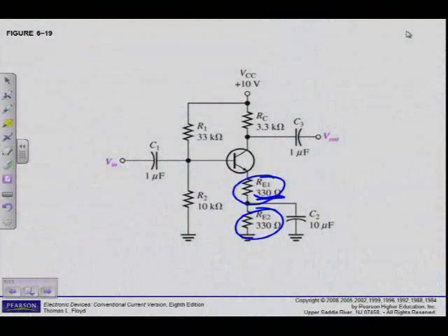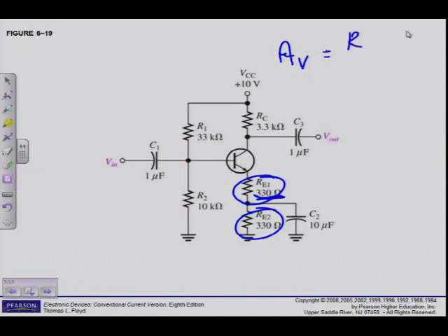Everybody uses the same book. Then we can just simplify this formula to RC over RE1. But please, you have to keep in mind, if I look at example 6.7, there is no load resistor. Again, if there's a load resistor, then I have to calculate R, lowercase letter c, which is RC in parallel with RL, which also influences my voltage gain, of course.